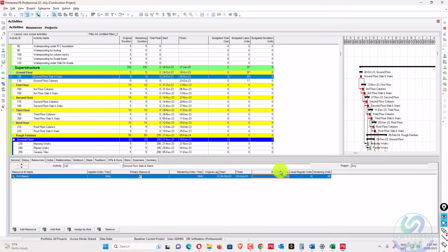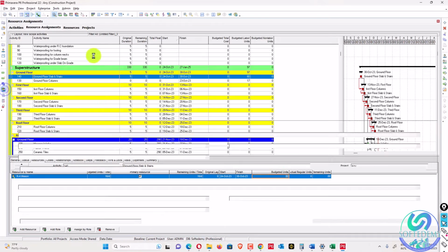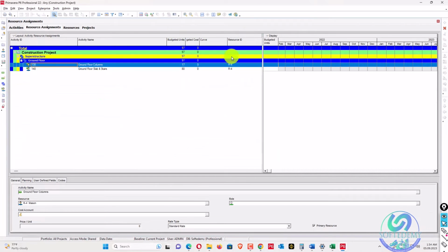So it is clear that in Primavera P6 there is no option for productivity rates, so that's why we are calculating in Excel. There is no place to calculate productivity rates in Primavera P6. Maybe in resource assignment you can assign a productivity rate user defined field, and by using global change you can divide your quantity.